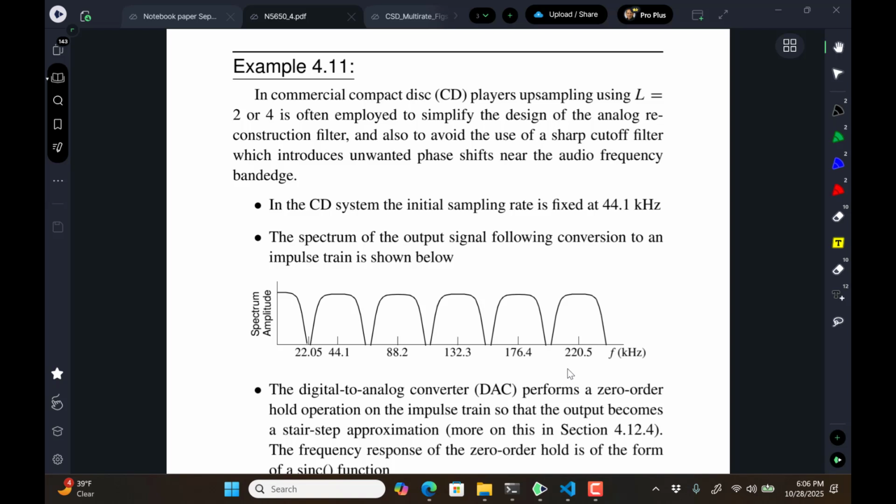Our human hearing tends to drop off right there, so we really don't need to listen to overtones and instruments and things higher than that. So the folding frequency is at 22.05, but you do need to roll off the content of all of this so that none of it aliases back down into this band. I think all of you appreciate that. I'm thinking of that one problem where in part B, you downsampled by 8 versus downsampled by 4, right?